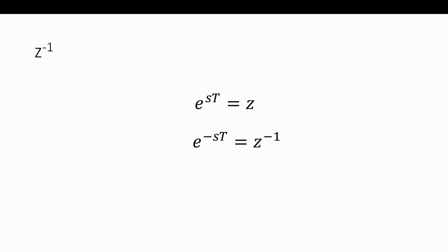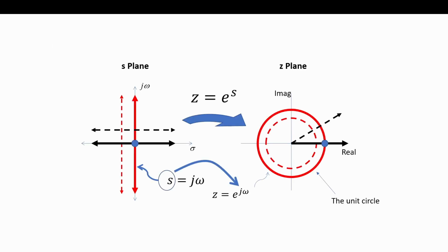And that's showing, if this part of the Cartesian graph here would be these polar radial things going out, and you can kind of see how the whole left half plane can come in. So this particular mapping that I showed you is called the matched Z mapping. There are several different mappings. They all have different advantages and disadvantages. The big thing is there is not a mapping that exists that preserves both the time and frequency characteristics of our continuous time system.